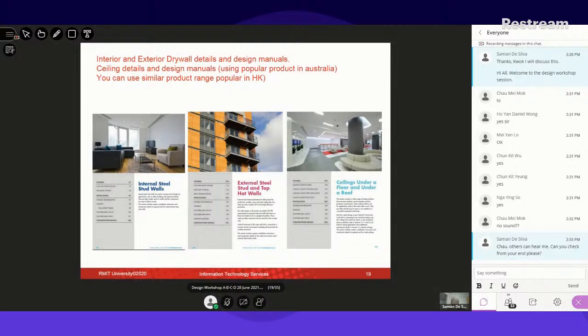What I have done here, guys, is show the internal walls you will have in your design. You have to have the external walls also identified, because other than the black lines that you see, you may require some external walls, and maybe some sliding doors for the balconies, as shown in the middle picture. These are called external stud walls, and then the internal stud walls.